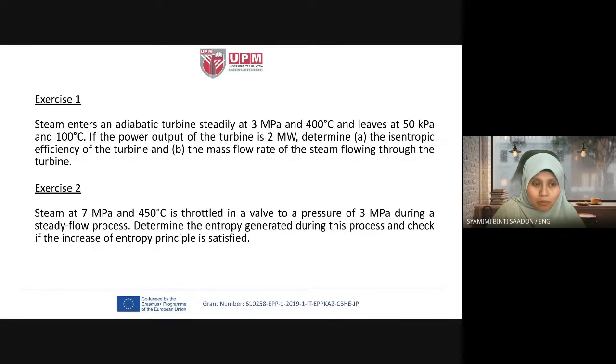Okay, it is steam. So we assume that the process occurs outside the mountain of the TS diagram. You have this mountain, right? Remember, in a TS diagram, inside here is only liquid plus vapor, here is vapor and here is totally liquid. So this is the isobar line. Inside the mountain, in the phase change region, it is horizontal, just like temperature. Outside the mountain, the isobar line goes something like this; it has a slope.